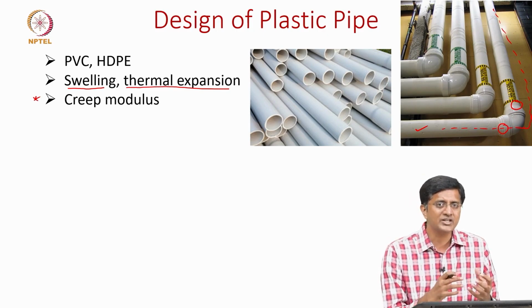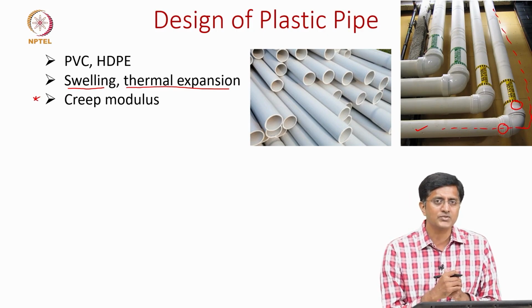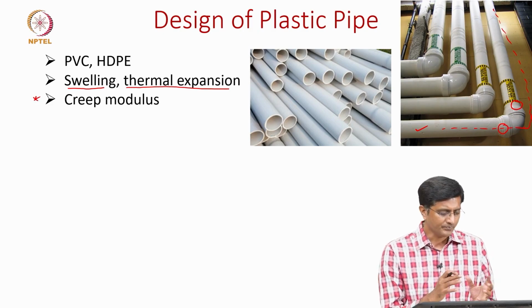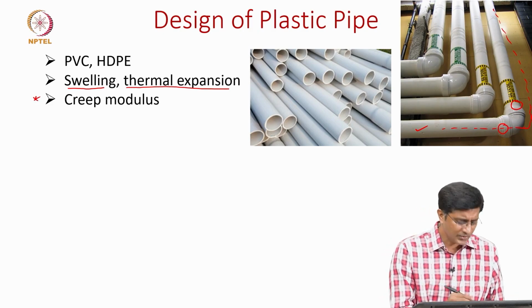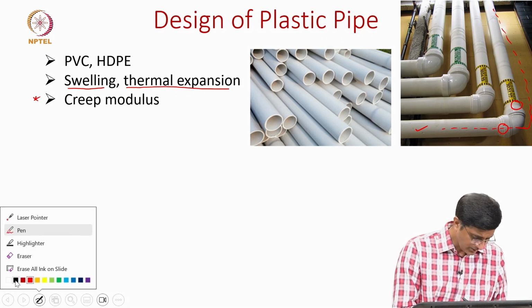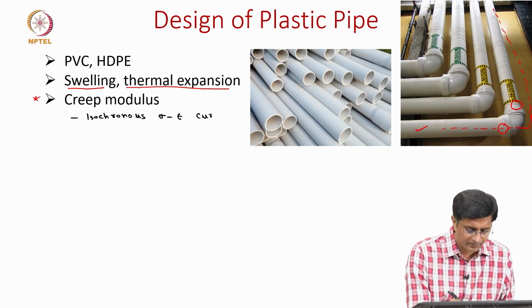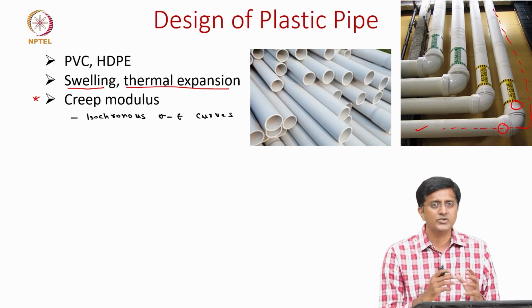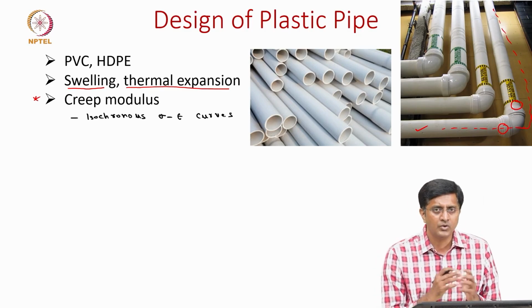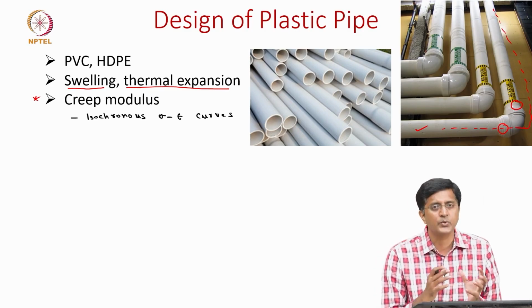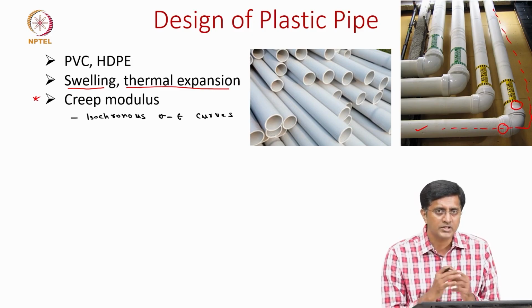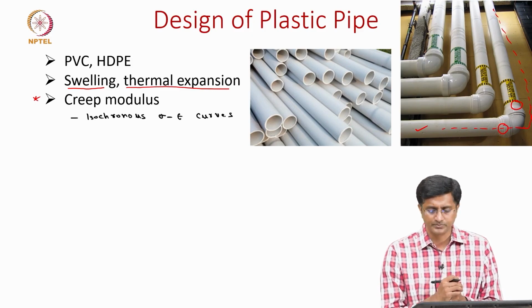Depending on that, there are standards which prescribe what is the creep modulus one has to look at. But again one can use those isochronous stress strain curves to help us with the initial design, to get a sense of what is the corresponding creep strain involved, such as to see whether these are in the permissible limits or not.